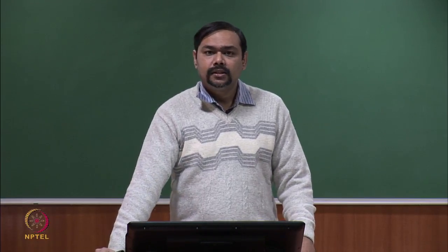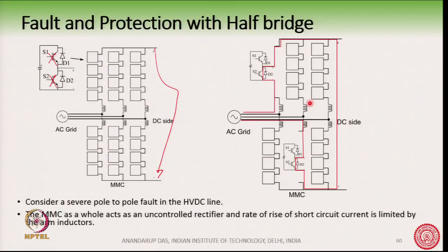Okay. The MMF which is getting impressed is very high, and so usually these inductors are made air core, because air core inductors are very hard to saturate. There is no iron, no amorphous core, no ferrite core involved in case of a low voltage. If we use an amorphous core, it is very easy to saturate it, but if we use an air core, it is very difficult to saturate.